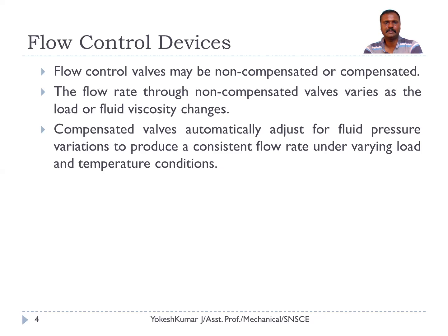So these are all the possible problems in the flow control valves since it is non pressure compensated. So therefore, we have to compensate the pressure to ensure constant flow rate. So the compensated valves automatically adjust to the fluid pressure variations to produce consistent flow under varying load and temperature conditions.